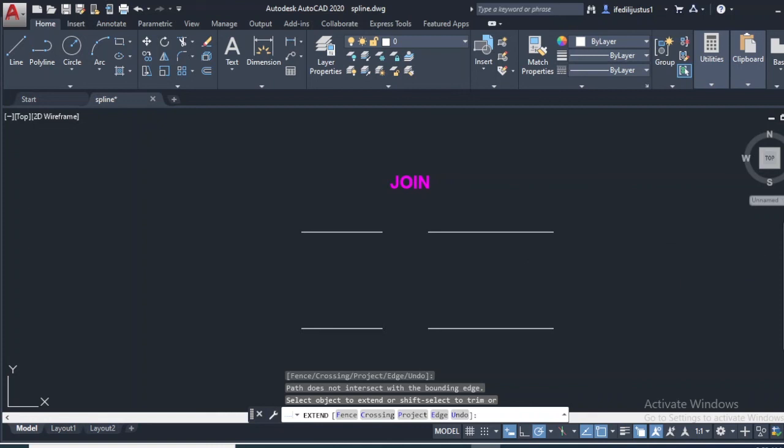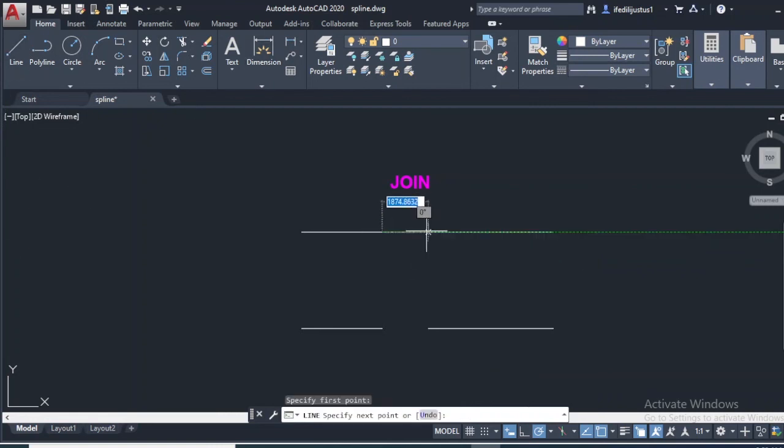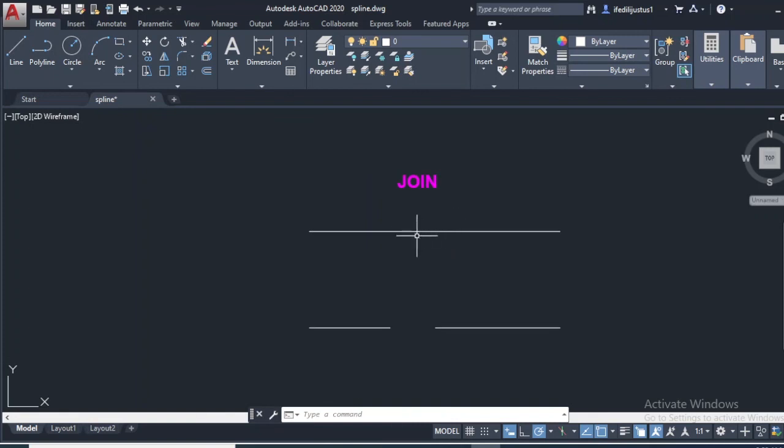You might decide to use a line command, you click this place, click the endpoint of this place, and you see the lines are being joined. But there's one disadvantage about this. If I want to select this object now, I have to select everything one after the other. The object is not totally joined, so that is one disadvantage. You see it here as being joined, but the lines are not joined, because once I want to select, I have to select the lines differently.